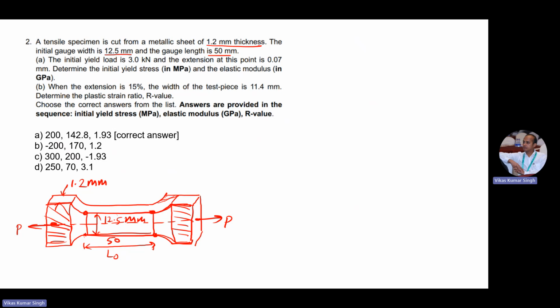For that we need a cross-sectional area which is lower than all the other parts. Like here, if you see, the cross-sectional area at these points is all bigger than this, which means whatever stress comes at this point will be lower than the stress in this region. So that's why we are keeping it like this, and this is to avoid the stress concentration.